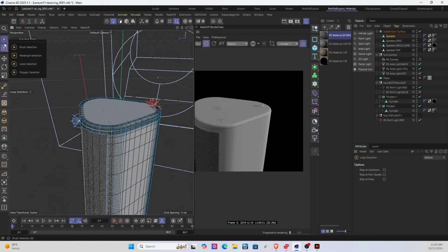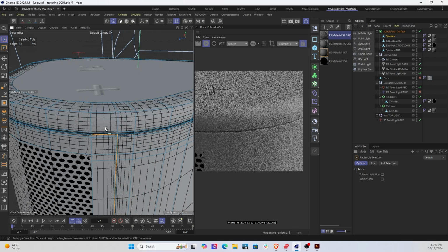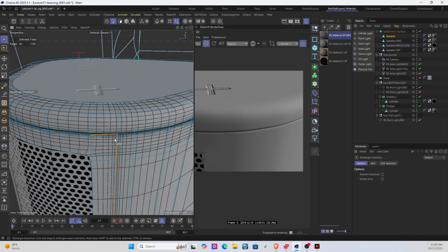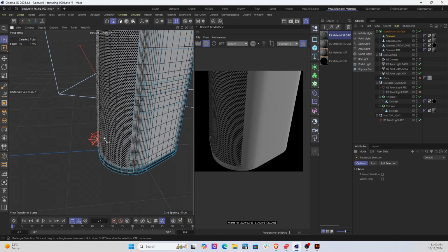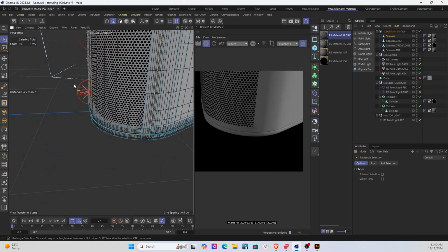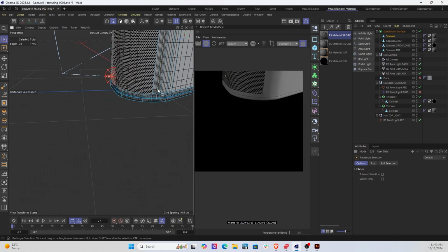So we can now go here and hit rectangle and control and keep the control button held. What that's going to do is remove the lines that we don't need, remove visibility so that we are selecting everything. So you can do it this way, right? There's nothing wrong with this way either. It's just sometimes if you want to be precise, you've got to basically select all the lines. Now here as well, we can see that we have selection. So let's just select all these lines, holding control. And that's it. So that's another way, much faster.